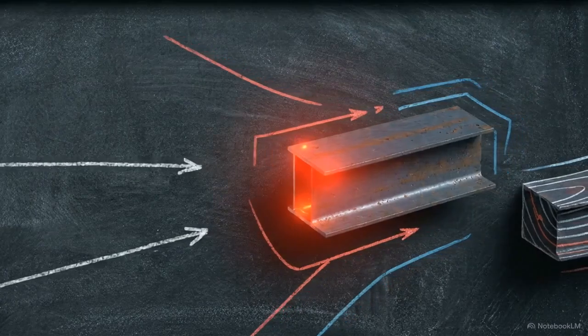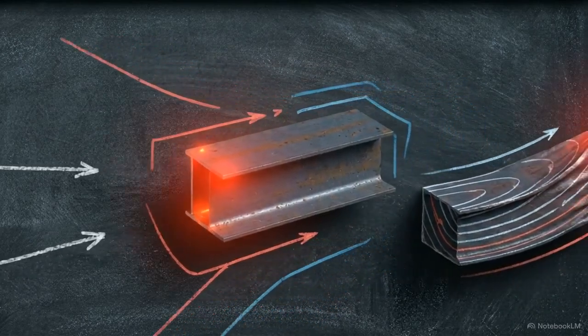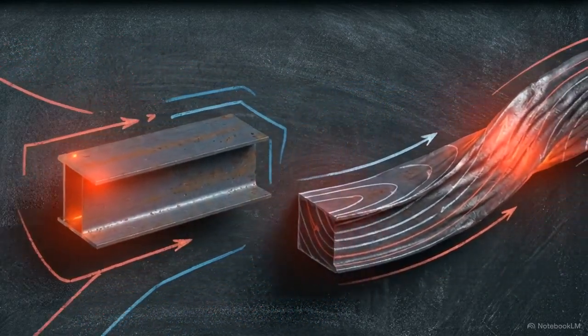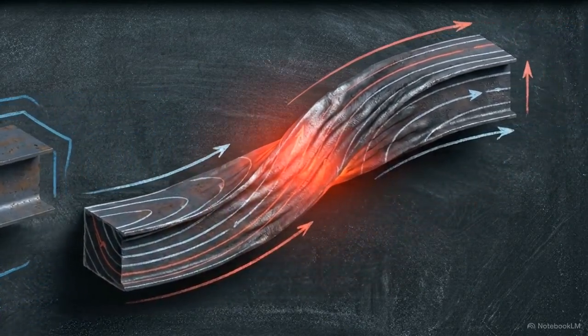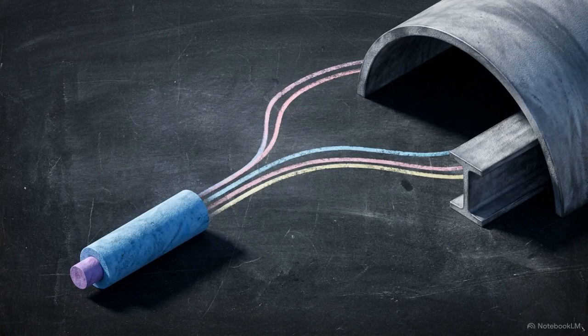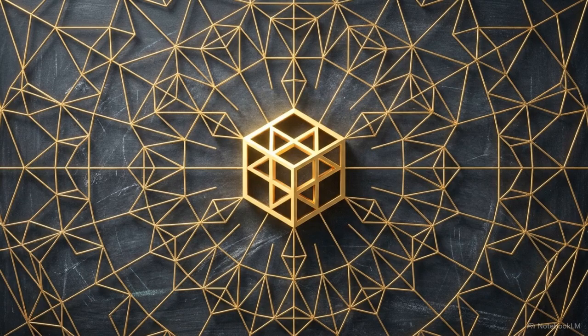This energy-based approach is particularly valuable for complex structures, where the governing differential equations are difficult to derive or solve directly. The same sequence of defining energy functionals and applying variations will allow us to derive models for more complex structural components, including beams. Hamilton's principle provides a foundational tool for finite element modeling, allowing us to derive the mechanics of a system starting only from its energy.